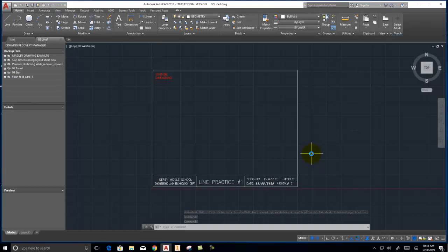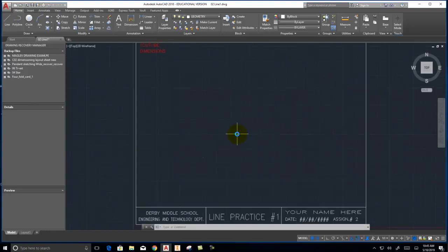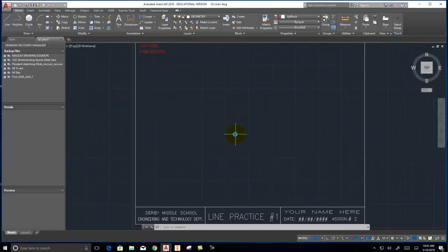When you click on the file, you open up something like this. It might not have a title block, but you'll be seeing something that we've prepared for you. If I have a drawing like this, there are a couple things that you need to notice. Number one, there's a grid in the background. This grid can be used to help you draw out things. So currently this grid is set to 1/4 inch grid, and the major grid is 1 inch.